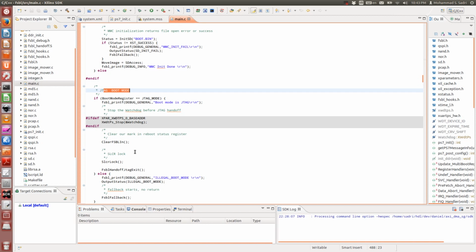And this program, which is supposed to be executed in all of these situations, should be able to handle all of these cases. But for us, what we want to do at the moment is to load our application to the ARM host through the JTAG, and then begin executing the code over the ARM host through the JTAG interface.